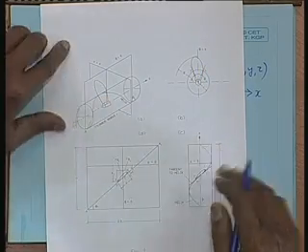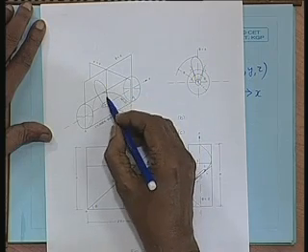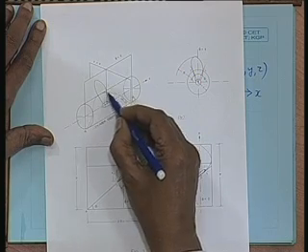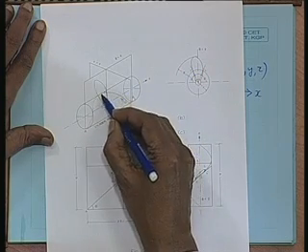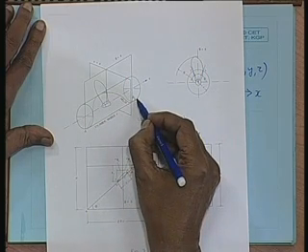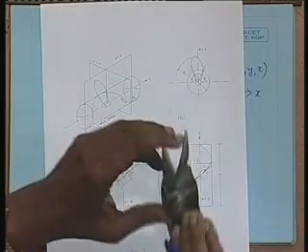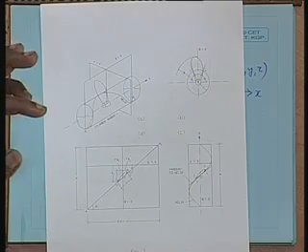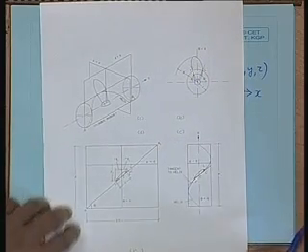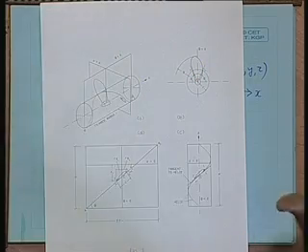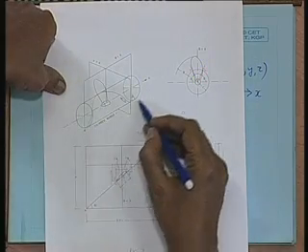Now, you see this is the face of the propeller blade. This is the face corresponding to the diagram we had seen earlier. This helix forms a part of that face, or rather the face forms a part of this helix that has been shown here. This part of the curve. Now, if I open this cylinder up, I have drawn this line on the cylinder, now I open it up. What do I get? You see here, this is a cylinder of radius r.